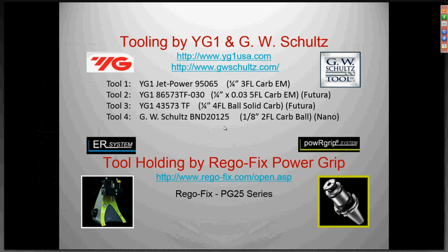You'll suck a tool out of even a heat shrink. So you have to look at this. If you're going to get aggressive with iMachining, I would recommend taking a look at some good tool holders. The Power Grip system from RegoFix is a real good system.